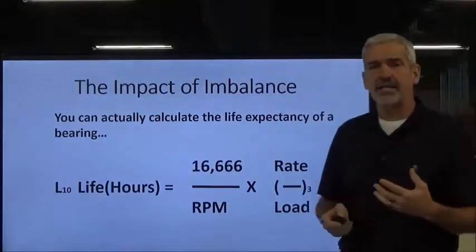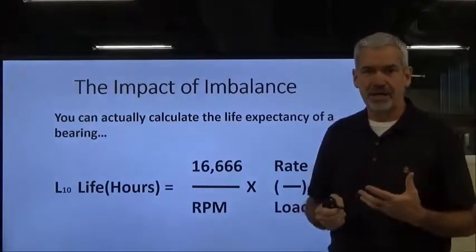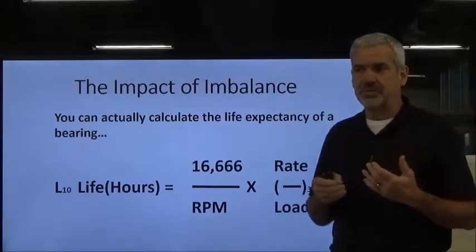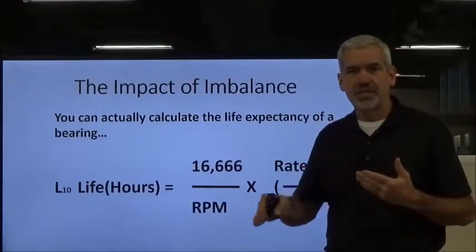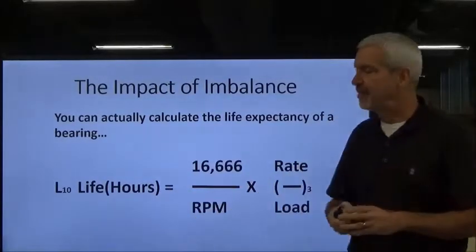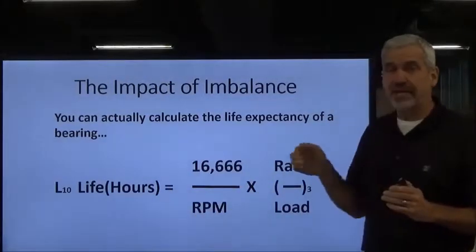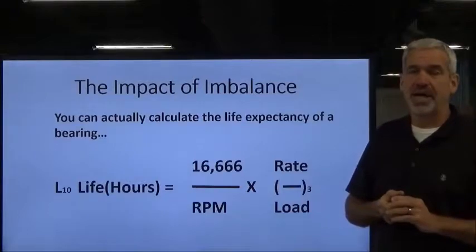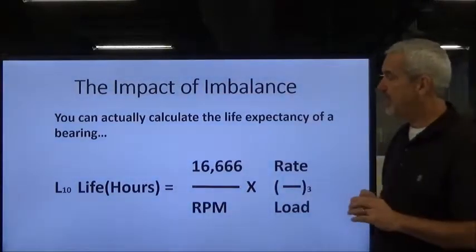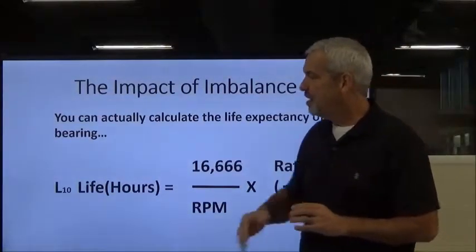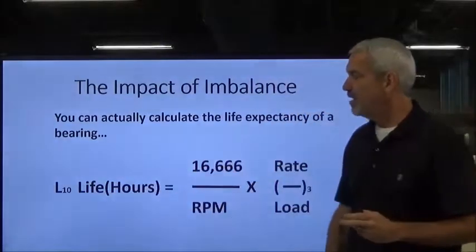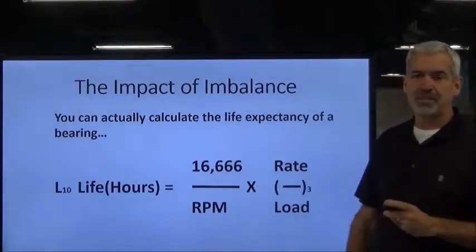Okay, and so when we talk about bearing life, we talked about it kind of heading toward its end of life the second we fire that machine back up. You can actually calculate and predict how long a bearing will last. There's a formula for it too. When we have L sub 10, that's the number of hours that a bearing is expected to last.